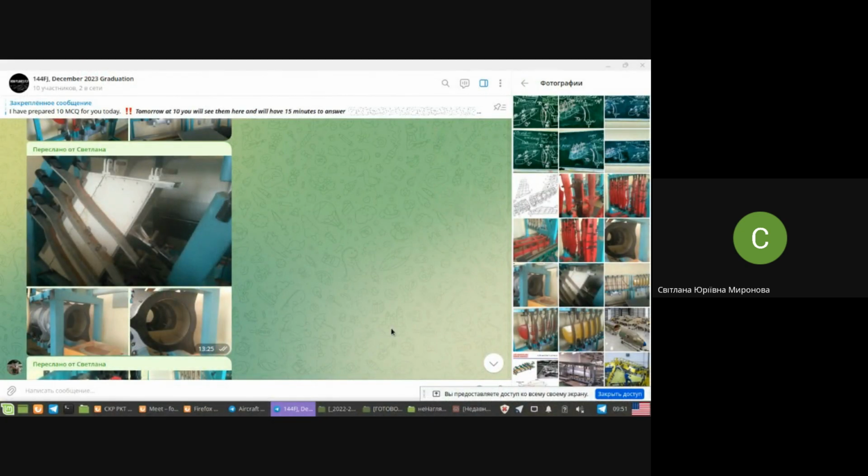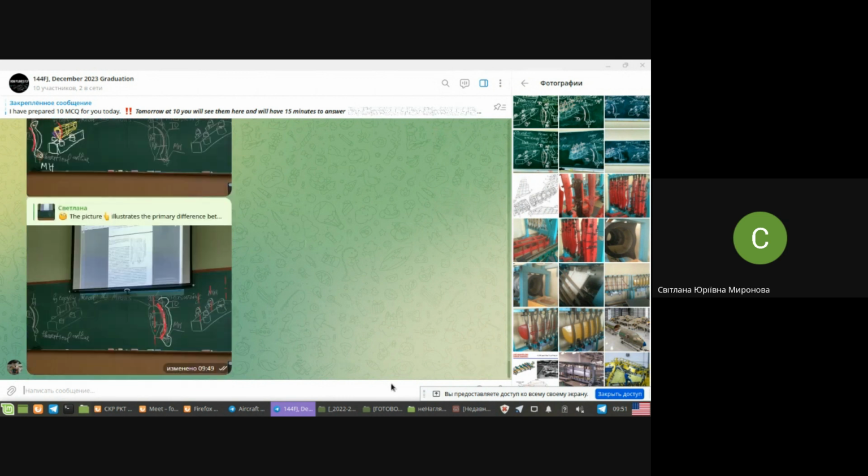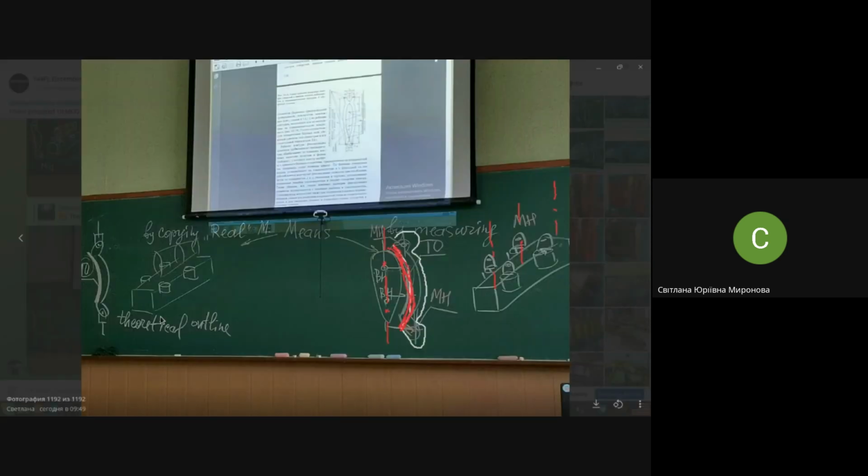Even axis of this pin, even axis of those holes that you might see. Axis, it's our imagination. It might be used for showing something in a drawing, for dimensioning. But in real life, you can't adjust your ruler or any another measuring device to the axis. To the object, yes, you may, but not to the axis. It does not exist in real.